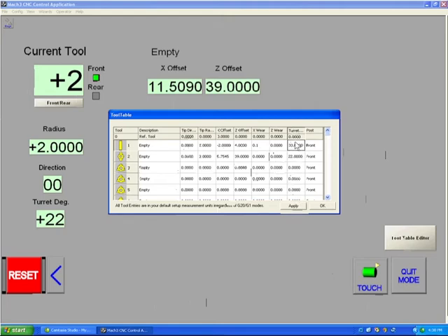The turret position is used for those who write macros, which can automatically switch tools using a rotational tool turret. They can grab information for their macros from this table, telling them whether or not the angle that they're currently at is appropriate, and then using a macro to adjust that angle. For tool post, we could select it as front or rear. The only thing that this does is switch from the G54 to the G55 offset system so that a rear tool can automatically be changed in its X dimension and its Z dimension so that the program knows that the same coordinate system it's using will be appropriate for a front or a rear tool post. If you use a rear tool post, you must at least make sure that your tool table is valid for it by using your part zeroing command on a rear tool at some point.